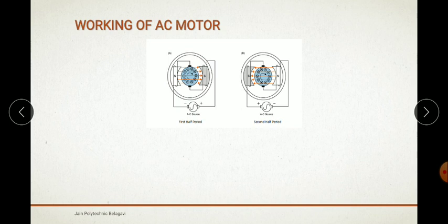And next, the coils are energized in pairs in a sequence, producing a magnetic field that rotates around the outside of the motor. Here, in the first half, you can see the direction from the north pole to the south pole, shown by the orange line. In the second half, you can see the direction is reversed, while the north pole switches from the left side to the right side, and the direction changes from right to left.